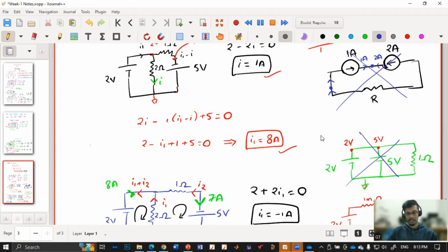So it is always vice versa. A voltage source cannot be connected in parallel, a current source cannot be connected in series, a voltage source cannot be shorted, and a current source cannot be open. But it is easier for us to think about voltage sources because voltage sources are readily available, but there is no ready-made current source. It has to be made using some circuitry, which you will learn in the future. Current sources are not directly available in the market, so it is somewhat difficult for us to think about them. But that is the case.